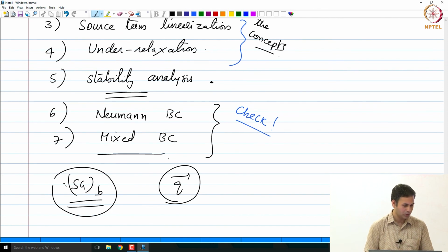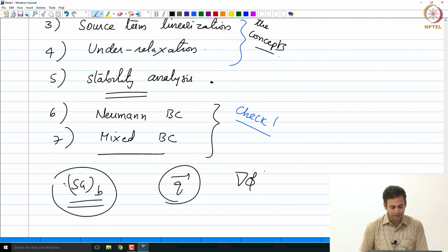Okay. So, that kind of finishes the discussion on the diffusion equation per se, on unstructured non-orthogonal meshes as well. We have one more concept which we have not covered, that is calculation of the gradients, which is what we have introduced. So, we have this small topic on the calculation of gradients for the dependent variable, that is how do I calculate grad phi.